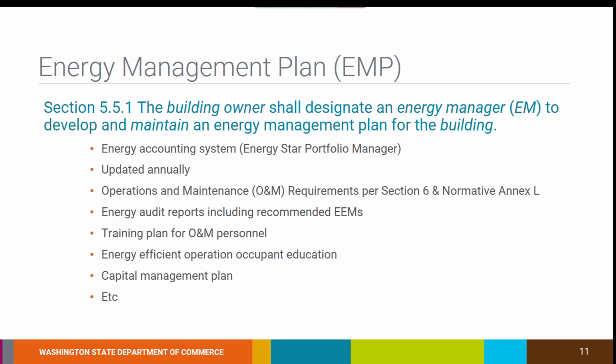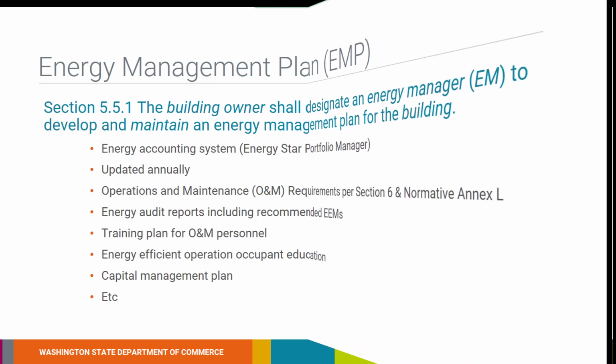Requirements for the energy management plan include development and maintenance of an Energy Star Portfolio Manager account for benchmarking and energy accounting purposes, development and implementation of an operations and maintenance program, documentation of energy audits, training for O&M personnel, a capital management plan, etc. Section 5 of the standard covers all requirements of the energy management plan.